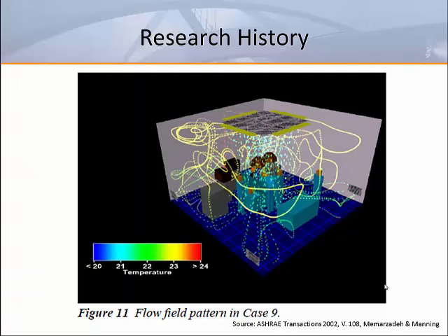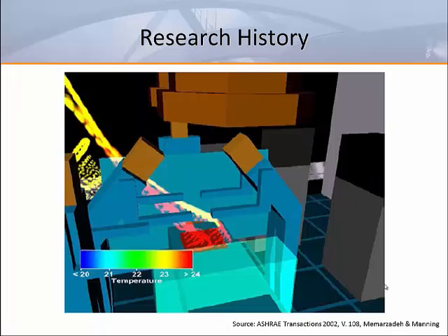generate thermal convection currents that can carry particles up to the ceiling level, where they could be entrained into the supply airflow and be deposited onto the wound or back table. By requiring a minimum array size and the use of diffusers with minimum entrainment, Standard 170 strives to reduce surgical site infections. That same 2002 study also demonstrated the presence